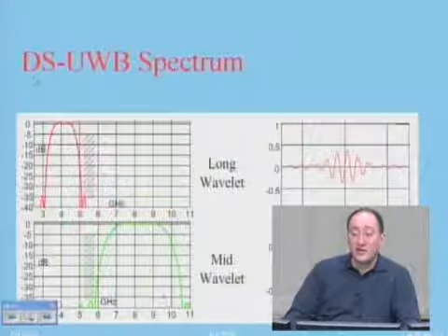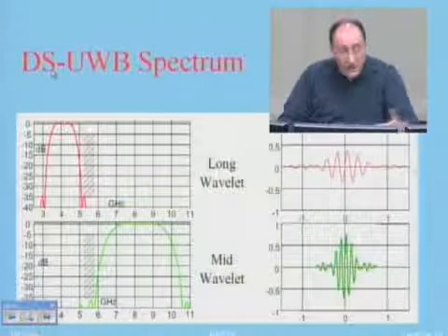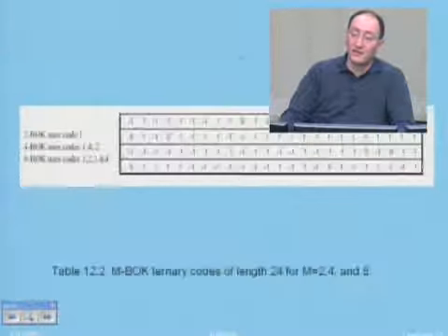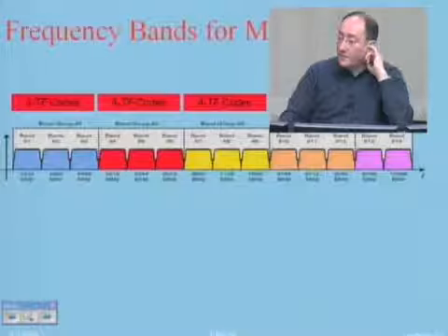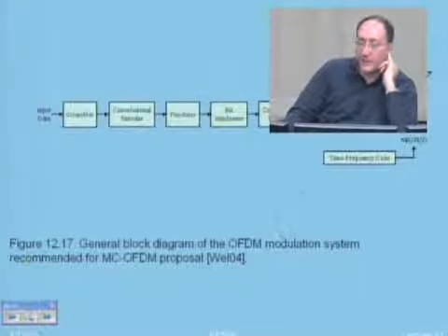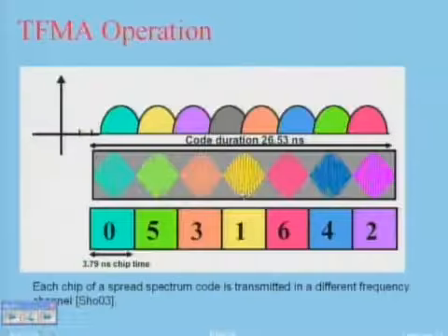And pulses are just direct sequence spread spectrum. They just go out directly. There's no OFDM in there. So that's the basic difference between these two technologies. This is a typical OFDM modulator that the standard body recommends, which is similar to what others that we have seen before.